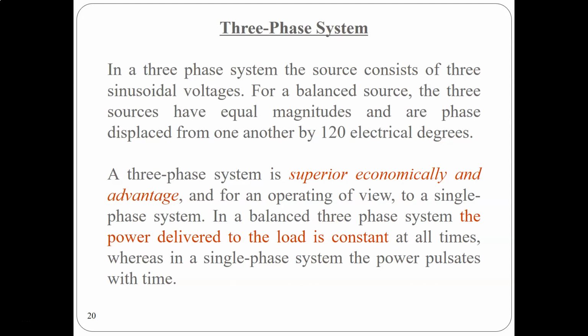A three-phase system is superior economically, and from an operating point of view, to a single-phase system. In a balanced three-phase system, the power delivered to the load is constant at all times. You will see that also a little bit later. Whereas in a single-phase system, the power pulsates with time.